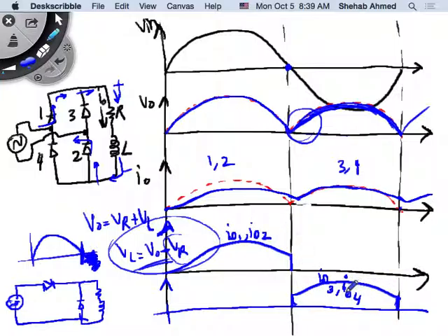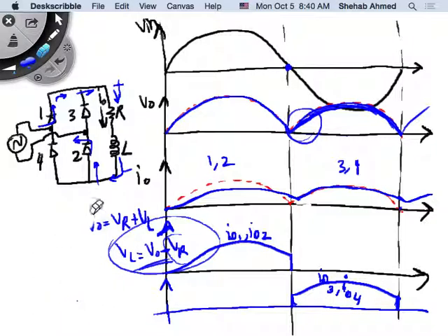How about if I ask you to draw the supply current? What would the supply current look like? This is probably not in the textbook, right? The waveforms that I asked about are not necessarily the waveforms in the textbook. They're the waveforms that you have in the circuit, but the textbook may be drawing a subset of the waveforms. That's why I recommend you simulate the circuit, look at the current and voltage waveforms everywhere, and try to understand how they look.